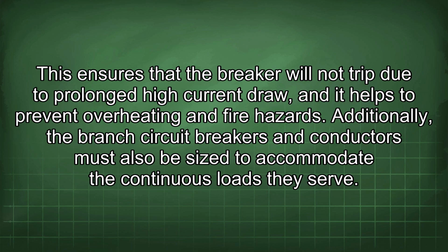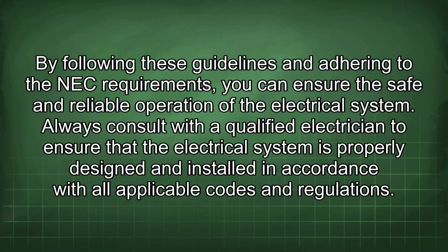and fire hazards. Additionally, the branch circuit breakers and conductors must also be sized to accommodate the continuous loads they serve. By following these guidelines and adhering to the NEC requirements, you can ensure the safe and reliable operation of the electrical system. Always consult with a qualified electrician to ensure that the electrical system is properly designed and installed in accordance with all applicable codes and regulations.